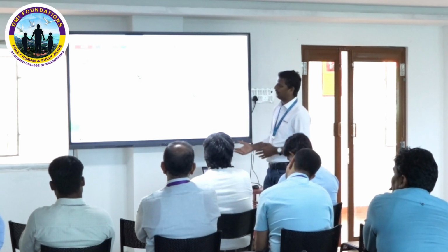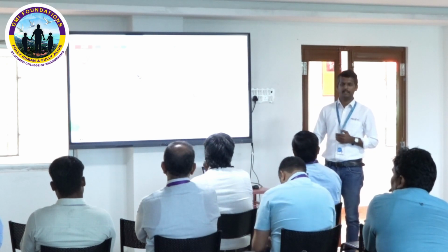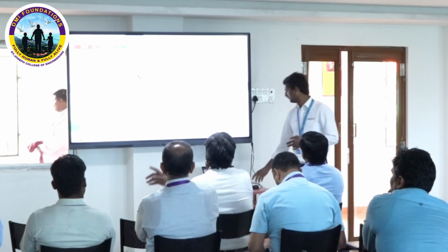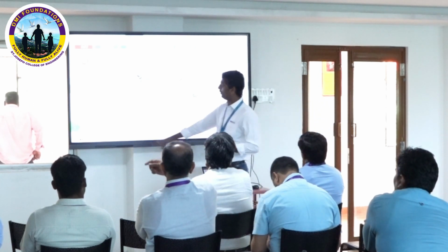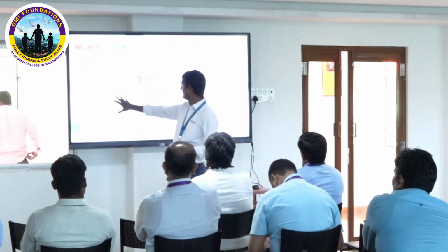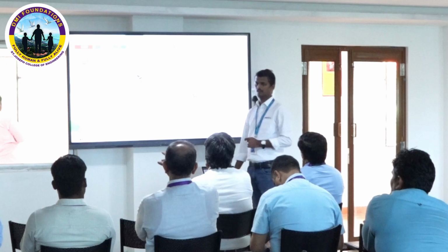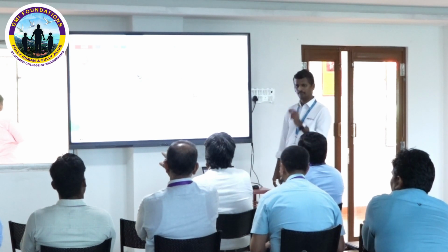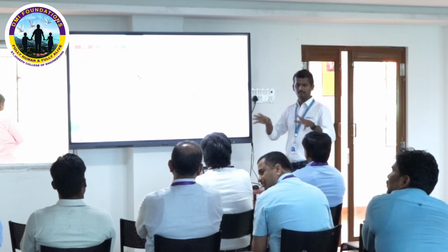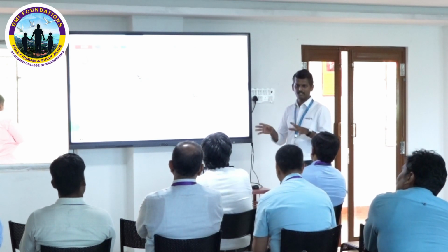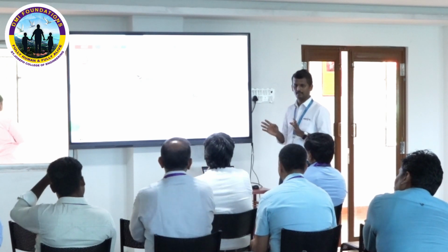In the automotive sector, when it comes to the racing industries, they try to implement this. Yes, this is 479 grams, the initial component. That has been converted into 248 grams. Yes, whatever component we saw yesterday, the functional basis we have to keep as is. We can't change the functional basis. It is the same. Only where the material is not required, those pieces we have to remove.